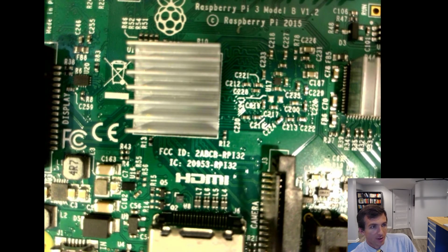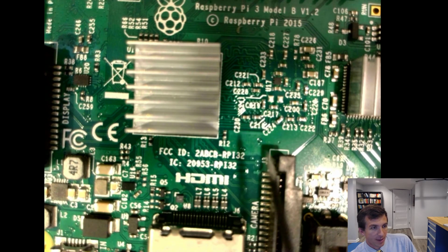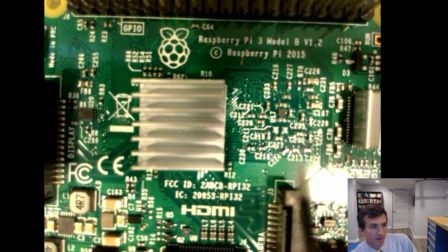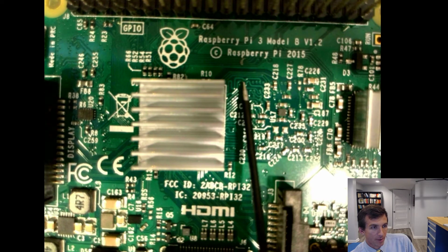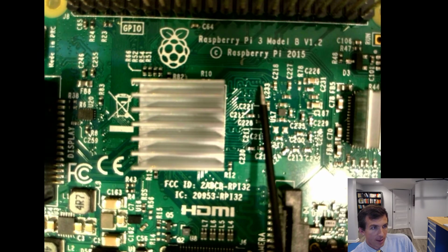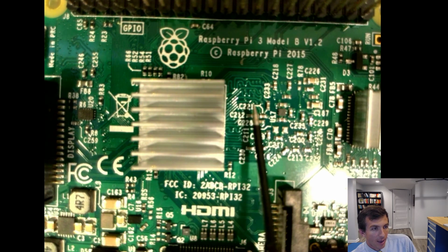All right, these are called meanders. And the goal with a meander is to have the distance of the wire be matched with all of the same kind of signals in that pair. Now, the impedance issue is more to the idea of why are some of them quite close together and some of them far apart, and we don't need to go there, but Davis, you are correct in that regard as well.